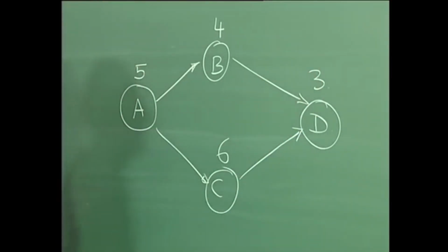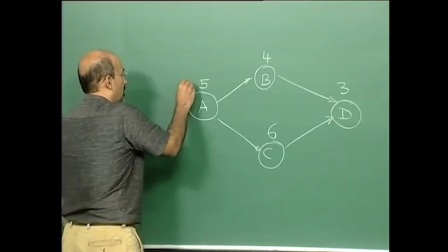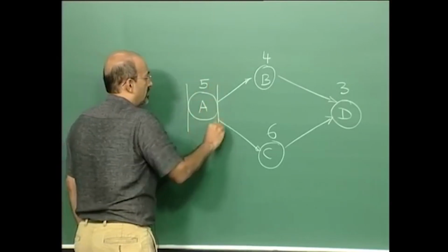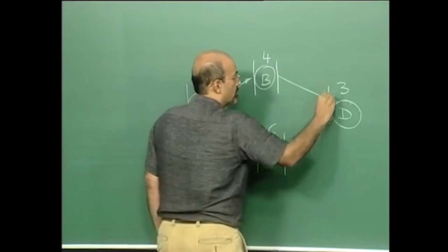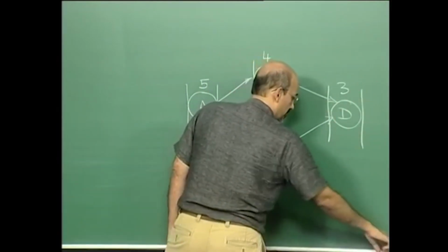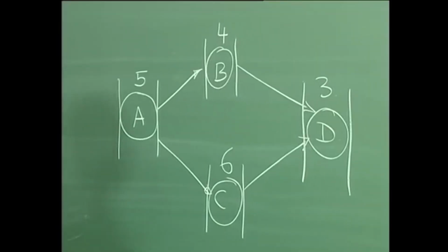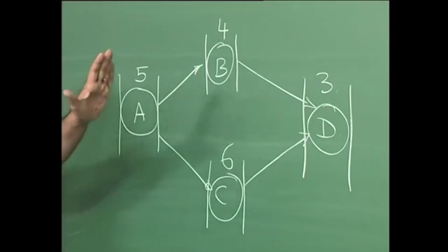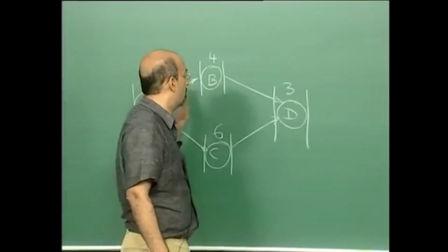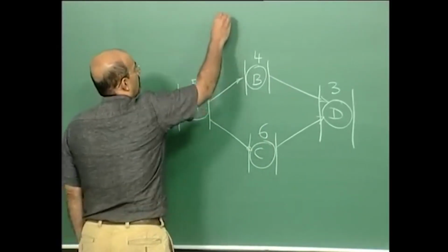I like to keep the duration, and as far as we are concerned, the duration is constant and fixed; we are not changing the duration for this analysis. I like to make a notation in this form, which makes hand calculation easier to interpret. Now we are going to calculate. This takes care of the first part, where we have represented the activity-on-node network. Now we are going to the second part, which is called the forward pass.